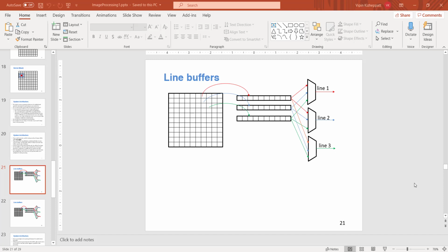Hello all. In this tutorial we are going to design the core logic of our IP core. We have already designed our line buffers, and we have already designed the logic sitting after the multiplexers, for doing the multiply and accumulate operation. This time we are going to design the module which instantiates all these line buffers and multiplexers, and which controls storing data into the line buffers, as well as sending data from this module to the MAC module.